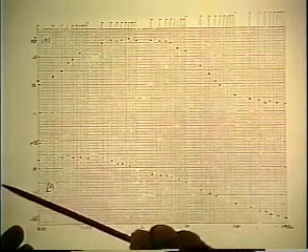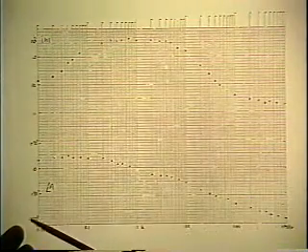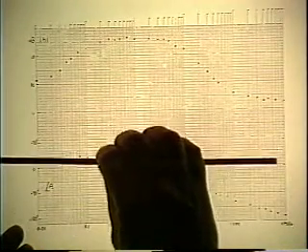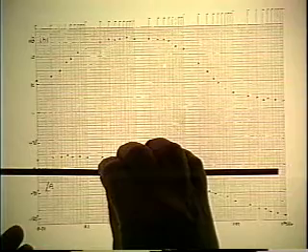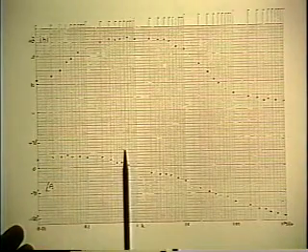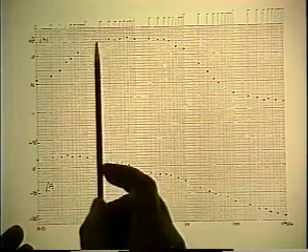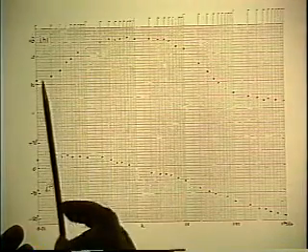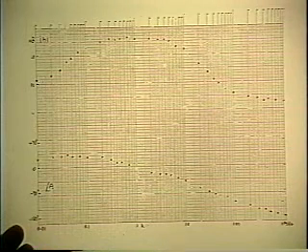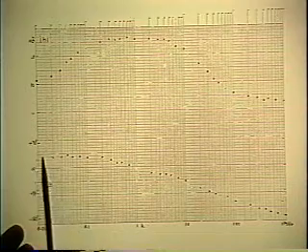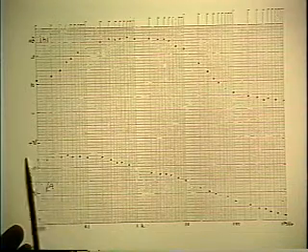Well, it looks as though it is. But now you have all the information you need, because the vertical position of the flat phase asymptote is determined by the degree of overlap. And we already know where one corner is, and if we know the overlap as well, then we can pinpoint the other corner accurately by using all of the phase data in the region of overlap.